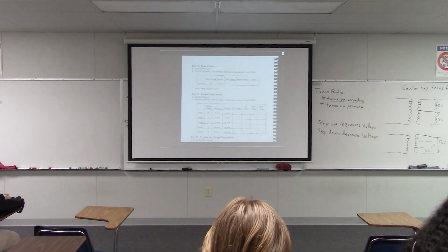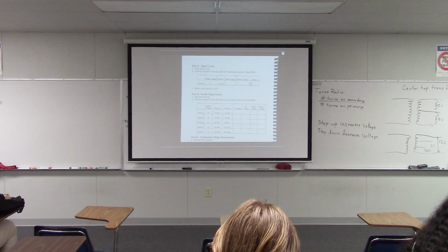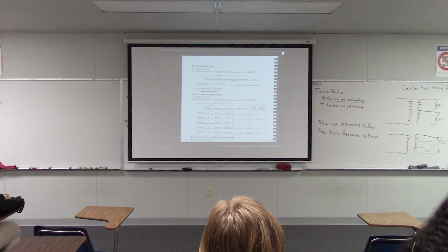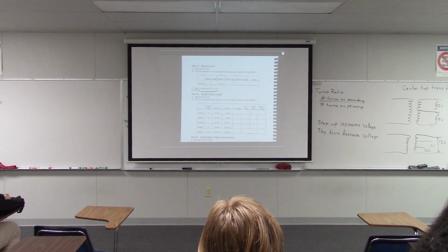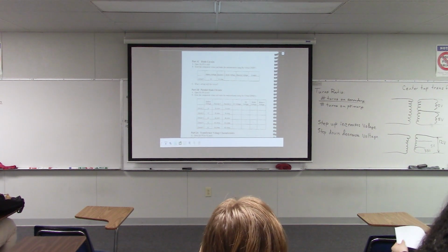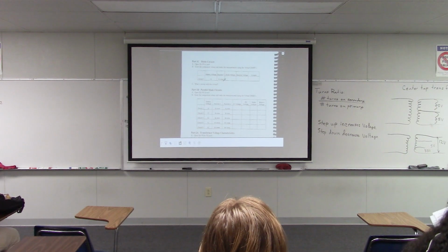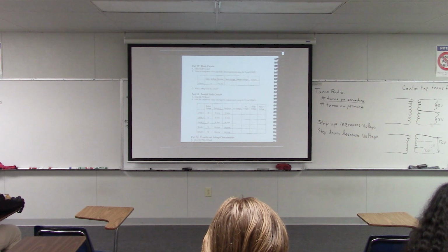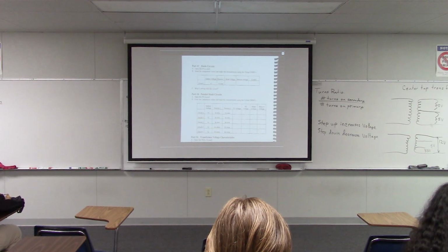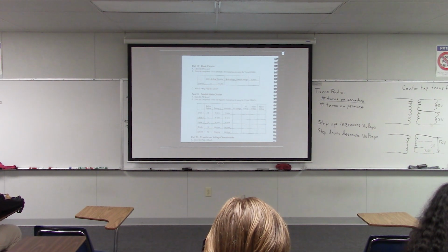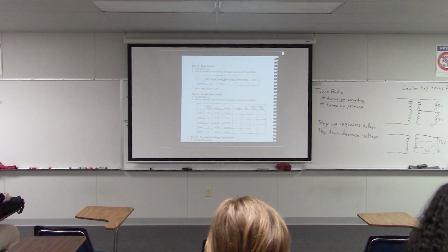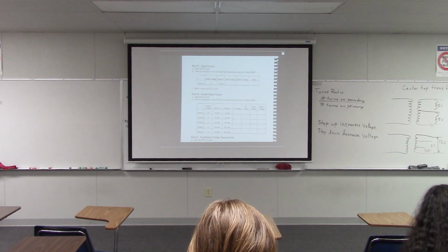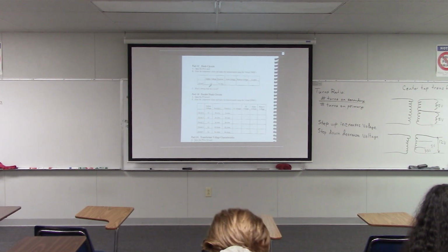So the lab book says you enter the component values and make the measurements here. Now this part says, what is wrong with this circuit? So what they're asking is, they want you to notice that that diode is reverse biased. But I wouldn't necessarily say that that's something wrong with the circuit. Like I mentioned earlier, some circuits are specifically designed with the diode backwards or reverse biased on purpose. So I don't know if I would say that that's something wrong with the circuit, but that's what the question is asking about. Okay.